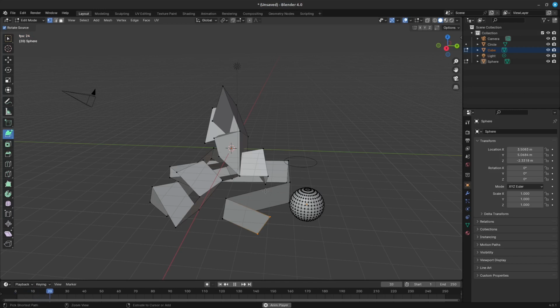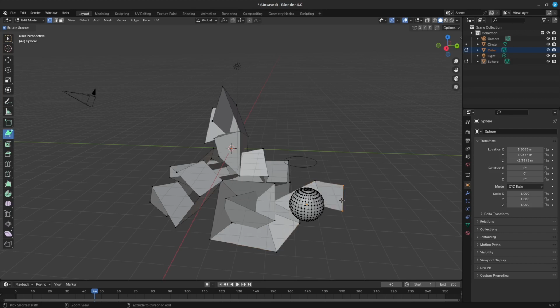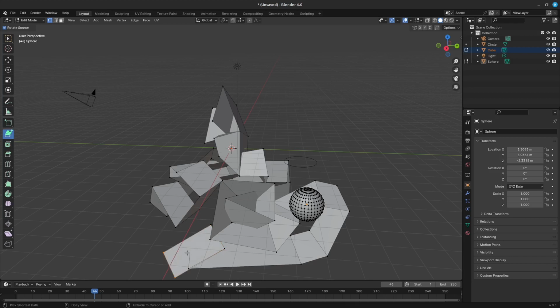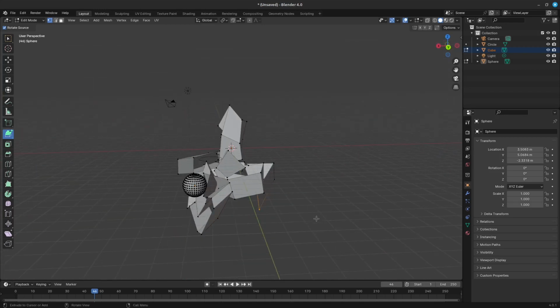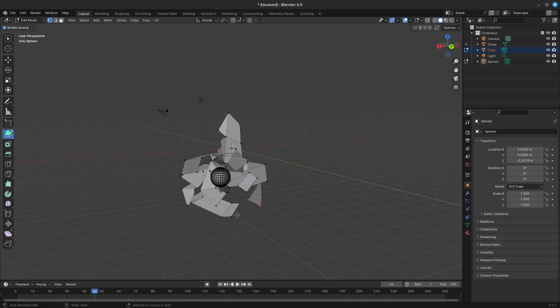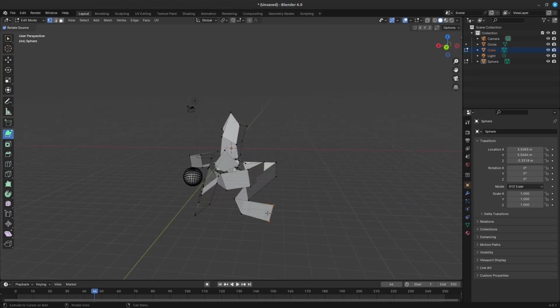But if you do not want Blender to rotate and smooth edges automatically, when extruding from Control plus the right mouse button, you can also inhibit Blender from rotating sources using the shortcut Shift plus Control plus the right mouse button. In this case, Blender will not rotate the source, dividing the angle between those edges when creating a face. If you have three or more vertices selected and Control plus right mouse button click, you will also create planar faces, but along the vertices selected, following the direction of the cursor. This operation is similar to an extrude operation.